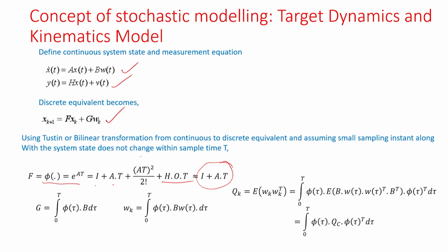Okay. There will be some error, but that is how it is. So, that is why I choose my sampling time a little bit lower, so that my higher order dynamics will not have any impact in my discrete equivalent. So, I can calculate: my continuous matrix times my sampling time plus the identity matrix will give me my discrete equivalent state matrix, or state transition matrix, number 1.